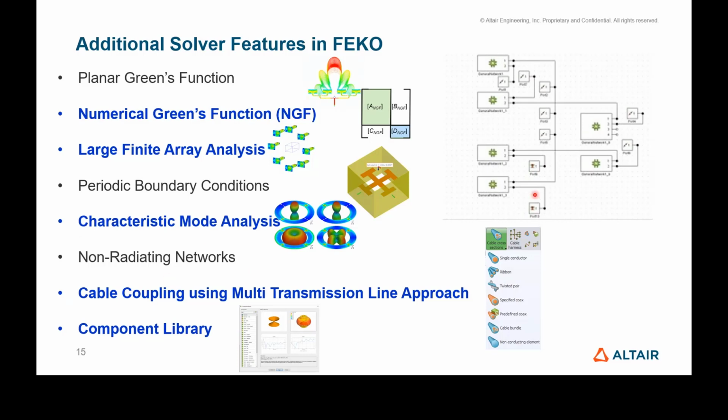This is also important because when you have physical structures that you model with CAD, you also want to add black boxes like your power divider or other devices that are connected to the antenna as S-parameters or a SPICE network, and so on, to the physical device.